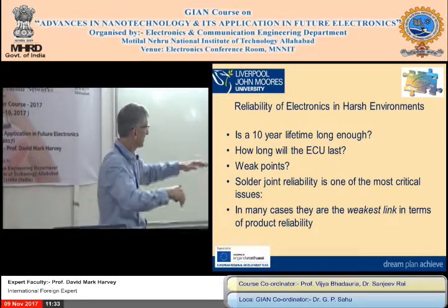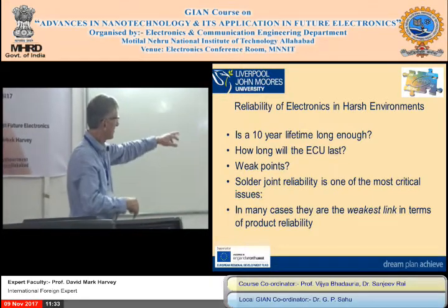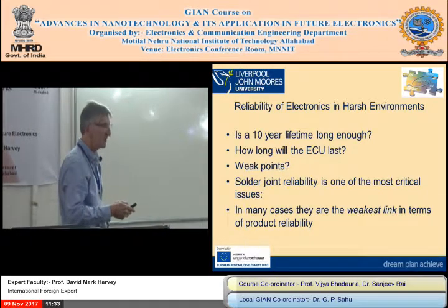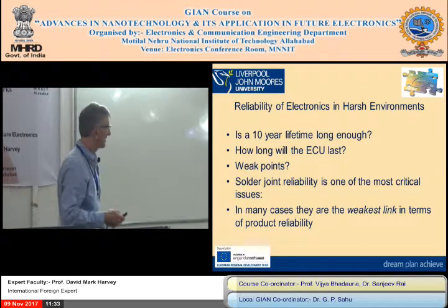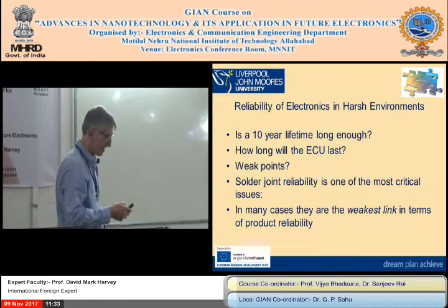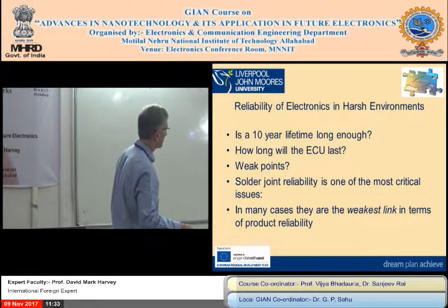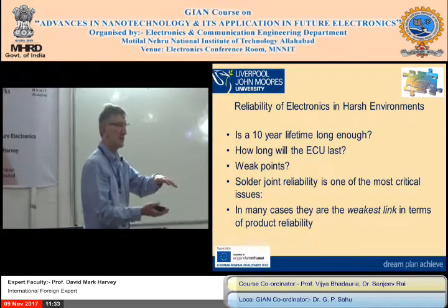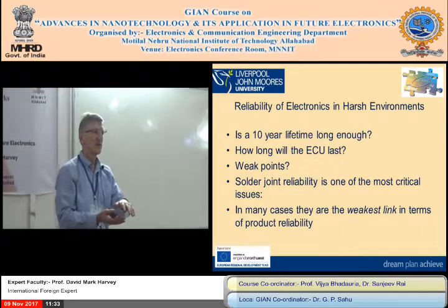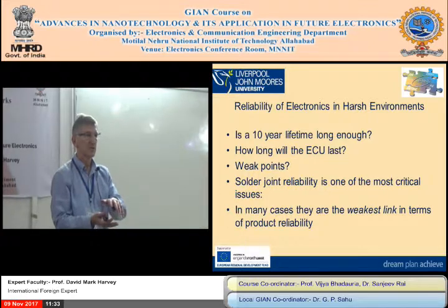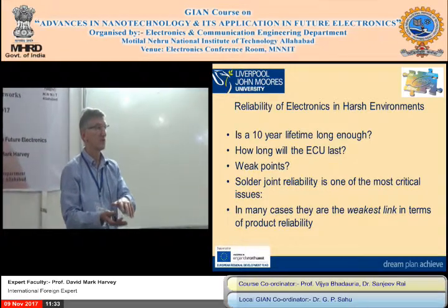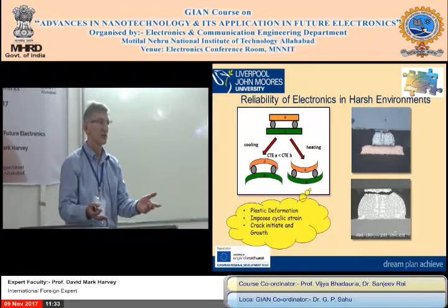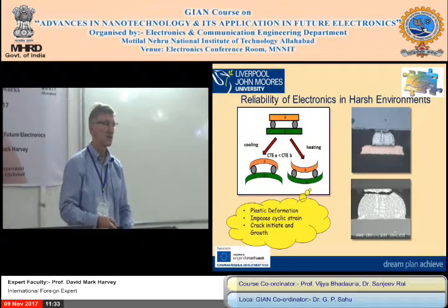So as it flexes up and down, you've got pressure on the joint, various things come into play, and eventually it's going to break. You're going to get some cracks. This is a section of a joint, so you see the crack under the joint there. So it separates. Once it's separated, mechanically it's not stable, so the chip will fall off the board if all the joints break. But once one separates, you've got an open circuit, it's in the bin or recycle time.